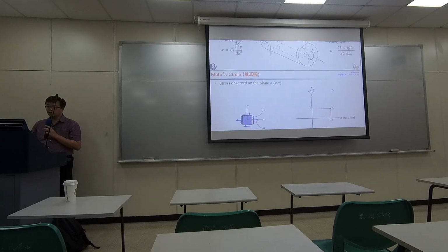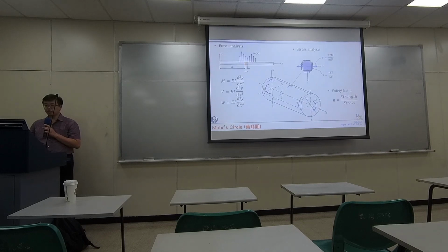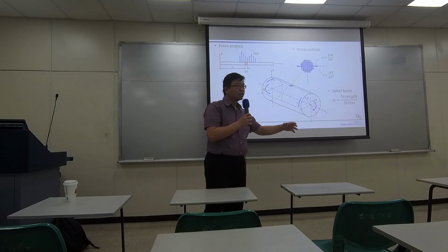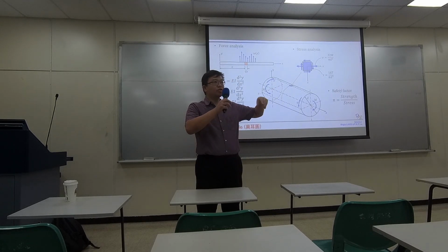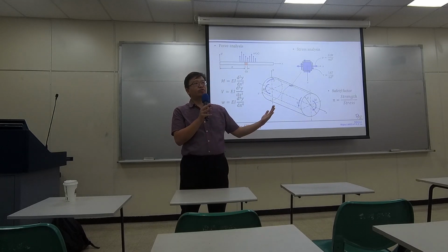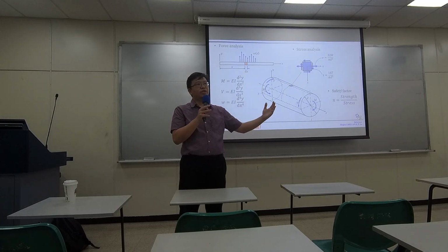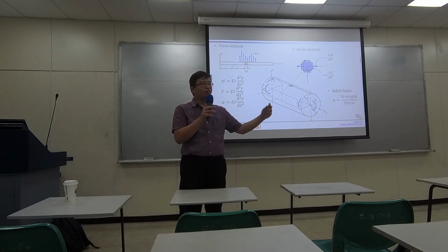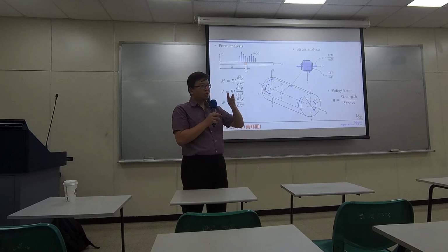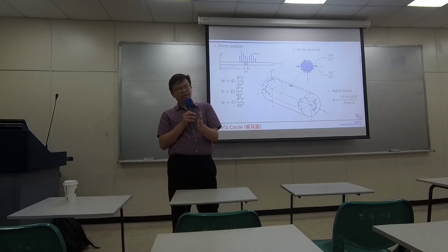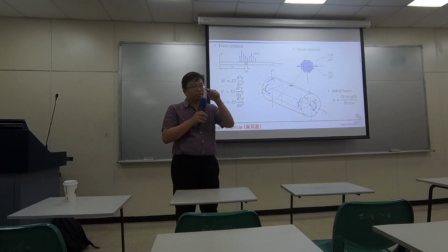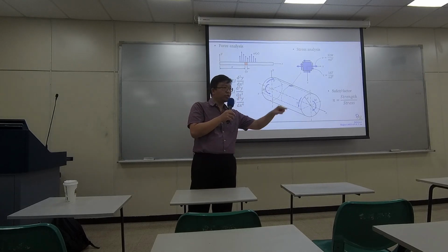Okay, so continue with what we had yesterday. I showed you one example about a shaft under various loads everywhere. So first we will have balance of forces, balance of moments to find out the loads everywhere. Then we will figure out the shearing force from the very left. By walking toward the end, we will figure out how the shearing force distributes.